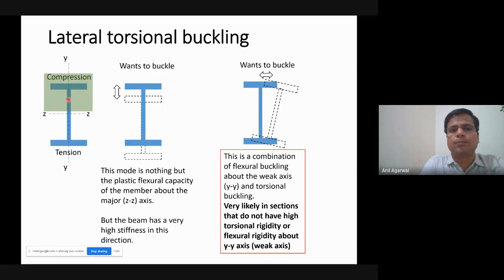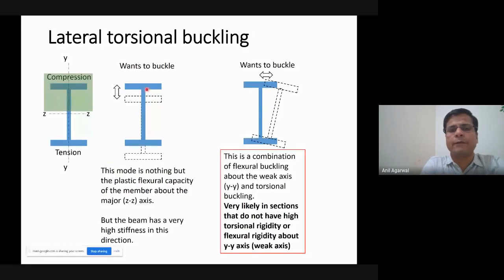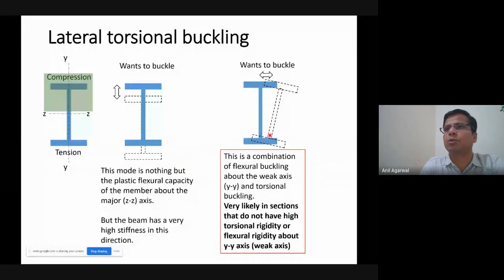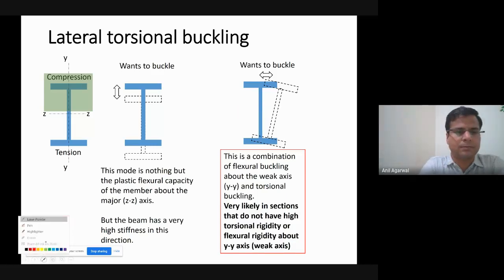And that is movement, right? So if this part wants to move away from this position in order to undergo buckling, it can go this way or it can go this way. It can go vertically down, it can go horizontally. If it goes vertically down, that will lead to the entire cross-section moving. That is not really buckling, that is regular bending. However, if it moves laterally away, like in the third figure, that is a real possibility. The top part that wants to buckle will move more, but the bottom part that is in tension doesn't want to buckle and will move less, or it will try to prevent the movement of the top part. So basically what you will end up with is a slight lateral movement.